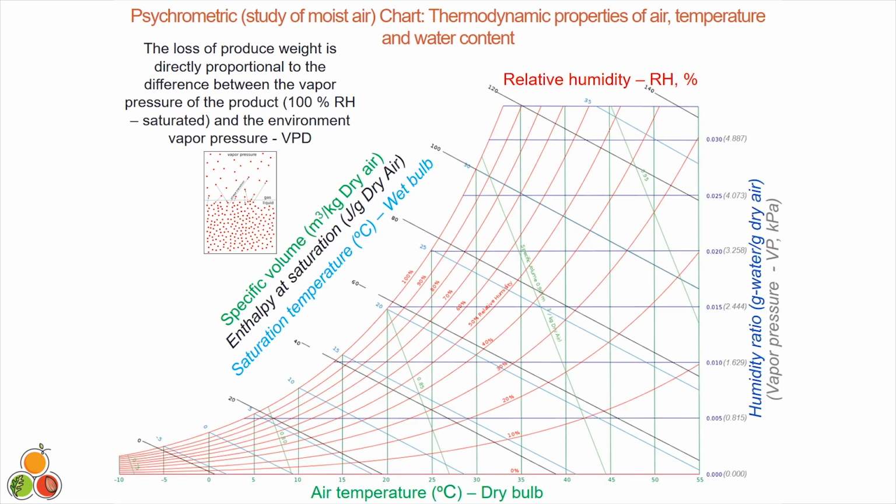So how important is relative humidity in comparison to temperature? Why are people not mentioning relative humidity? I've been asked this. My cooler, I don't care at what temperature it is, but I get all my floors wet. They're soaked with water, so I'm not losing any moisture. Is that accurate? Really? Who would say that's okay? I don't care about temperature management because there's water particles everywhere and I'm getting no moisture loss, if that's what you're aiming for. Well, psychrometrics showed us that that's not the case.